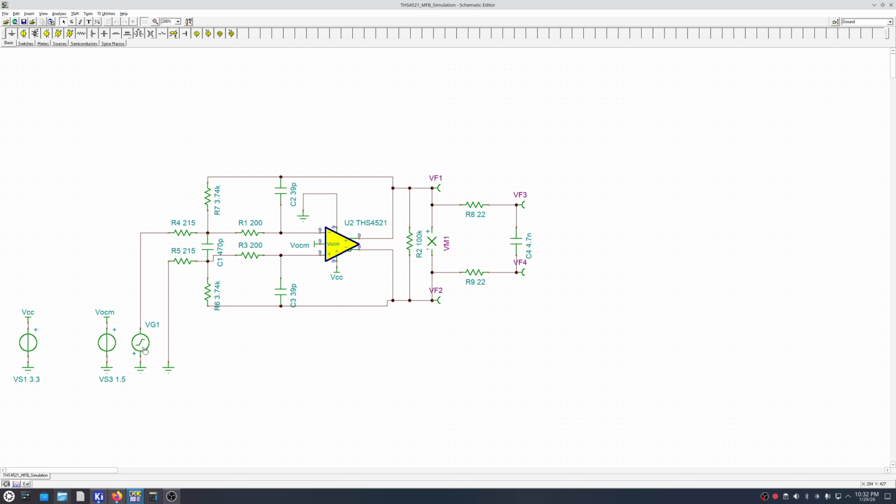And then here's the pulse. This is the actual shunt on the design. And then I have the components here. And this is the MFB filter with the like 17.39 gain. And then this is like extra charge bucket for the ADC.